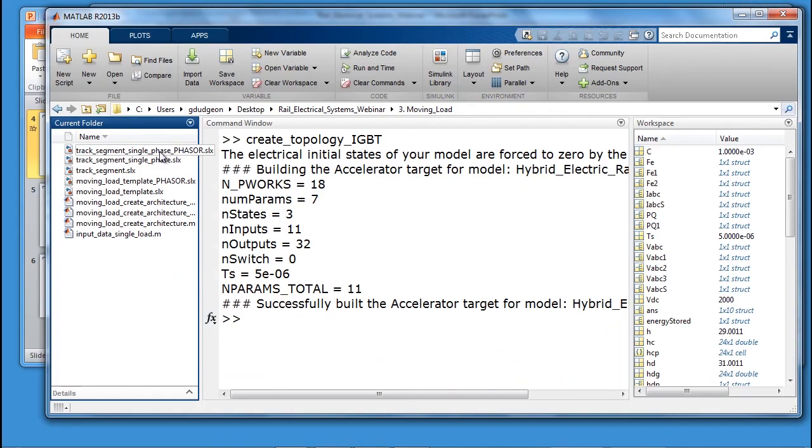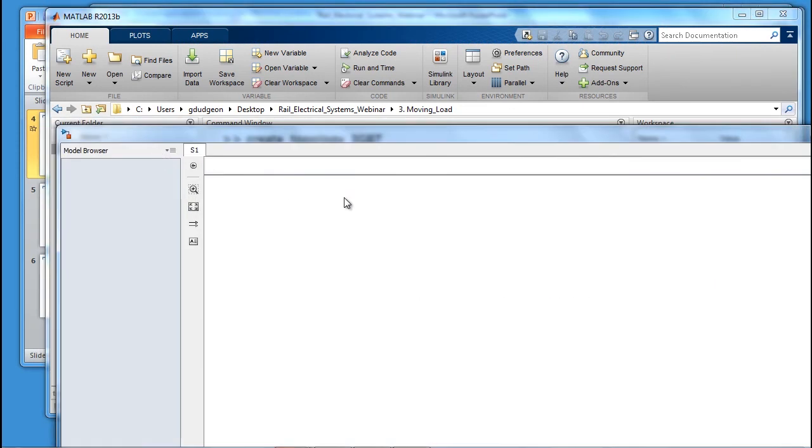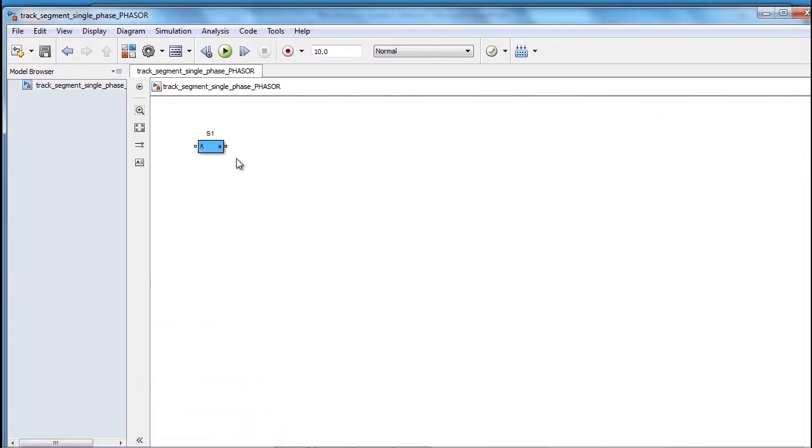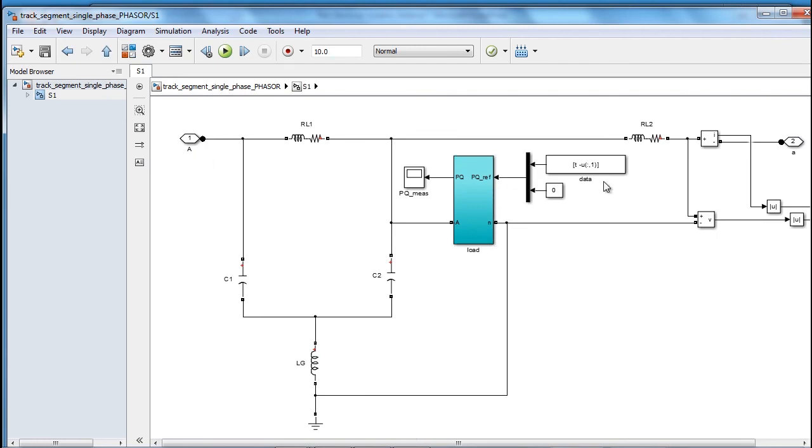So just like we did with the modular multi-level converters, let's look at the single elements that make up the system. So a single lump parameter segment, if I look under here, I'm basically going to be feeding signals in, and I'm just feeding active power for this particular example. I'll show you how to generate these signals in a minute, but we're basically feeding in these triangular waveforms for each segment. I just have a fairly simple representation of a segment here.